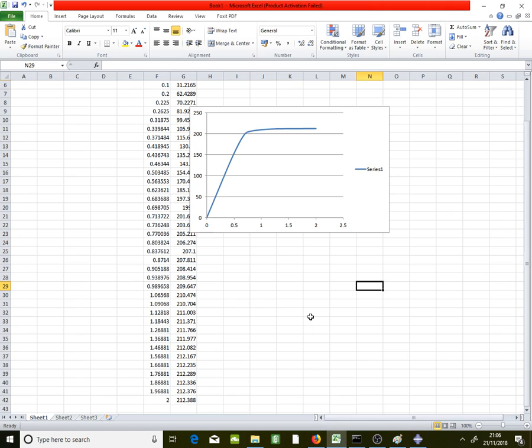So you say equals 625.268 times 1000 to convert to newton, divided by 200 as the width of the plate times 4 for the thickness, which is the cross-section area of that plate, that's 781.585 Newton per millimeter square. Note this point, note it.